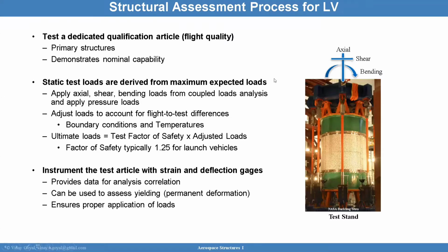So let's go back and discuss some of these things in more detail. You have this bending load, this axial load, this shear load, and hopefully your test stand is able to introduce these loads. If it's not, you may want to find a way of enveloping, with whatever loads you can apply, every critical failure mode between test and flight. You want your test to be worse than in flight, so you want to make sure the conditions in the test configuration are worse and envelope flight.